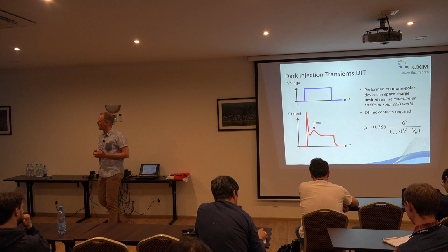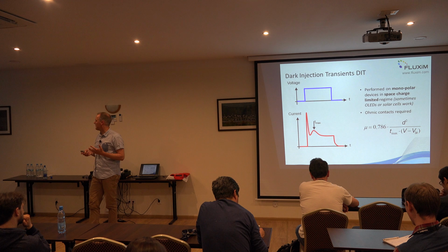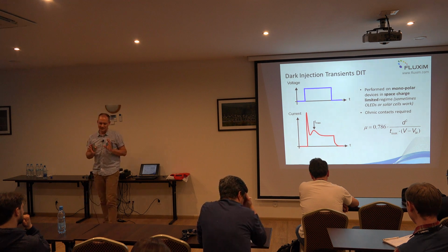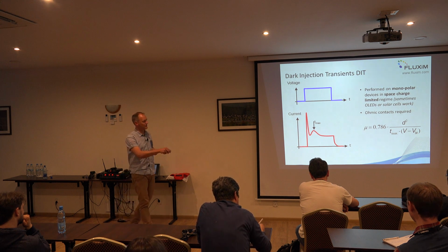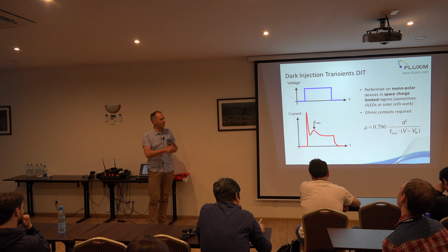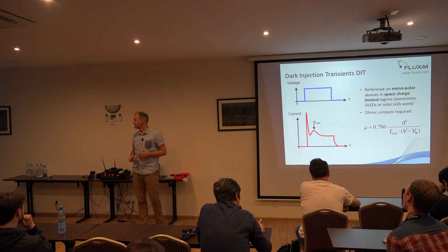It's namely the RC time effect, that the RC will lead to a strong increase and quick decay. So if you have good devices with a short RC time, then you indeed will discover the peak that you're looking for. If the RC time is too big, then it will be hidden in this first tail.